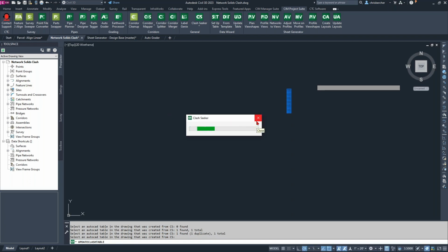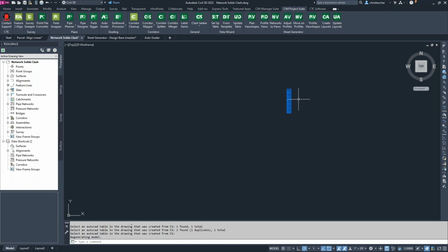And if it finds any differences, it's going to show you those differences. The more familiar you are with the Clash setup process and what's in your drawing file itself, the more you'll be able to see the changes made to this and track issues being resolved as you work throughout your process. This unfortunately was the longer table, had the most clashes in it, so it's taken a little bit, but that's okay. That's what it's doing. Things aren't going to happen instantaneously always, especially when working with larger clash reports. So even then, that wasn't that bad.